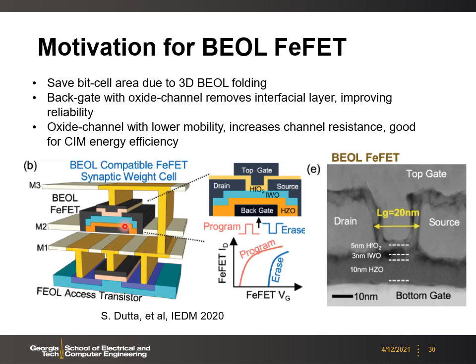In this particular case, it's the indium tungsten oxide. And then the HZO ferroelectric layer is deposited between the back gate and the oxide channel. Short channel behavior with gate lengths as short as 20 nanometers has been demonstrated in this work.